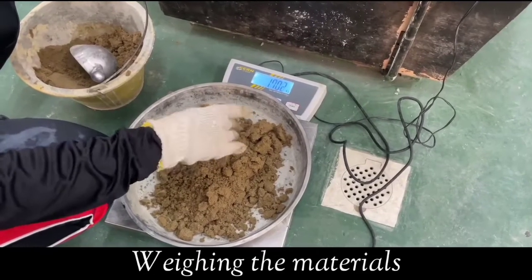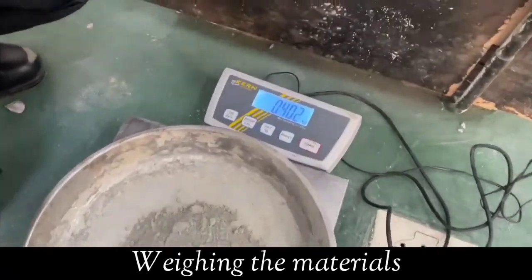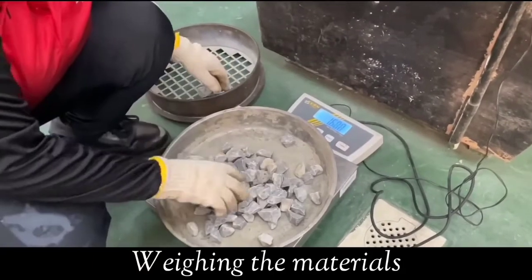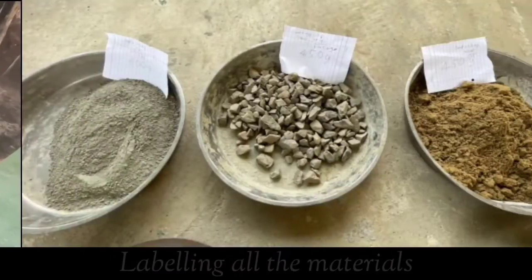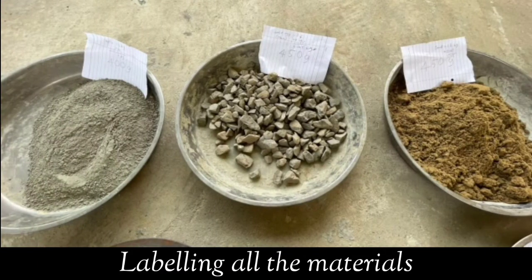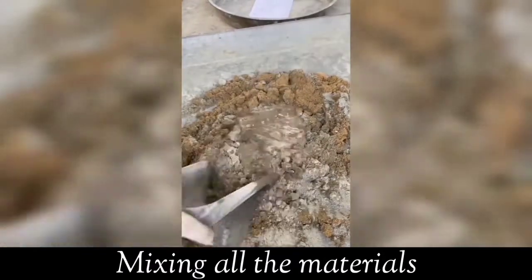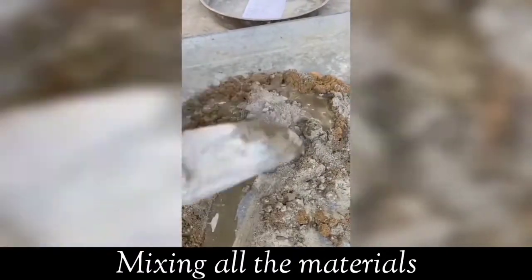The sand, cement, and coarse aggregate were weighed on the weighing balance based on the concrete mix design that we have calculated. All the materials are labeled inside a metal tray. Make sure each concrete cube mold has the same weight of materials. All of the materials are mixed on a metal tray until the mixture is roughly blended.